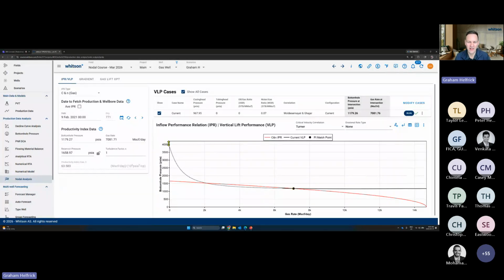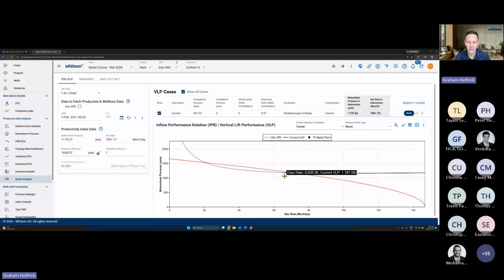But I can see that we're very close, like we're almost liquid loaded, and that's consistent with the previous plot that we just looked at, right? So it may be time to lower the wellhead pressure or to put some tubing in the well to delay liquid loading, okay? So we're going to wrap this gas example up and then we'll have a break, okay?